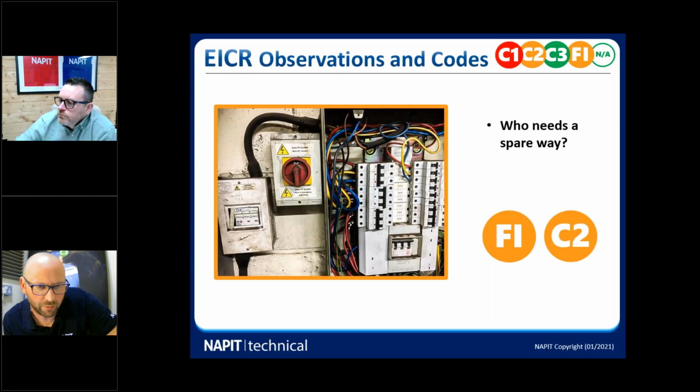You can see the blanks not fitting properly in the front of that enclosure on the left hand side there. There's also a lot of dust and grime, which usually happens in an industrial environment. So maybe the switchgear should be enclosed a little bit better than what it is. So there are things you need to be checking there, but it certainly is a C2.